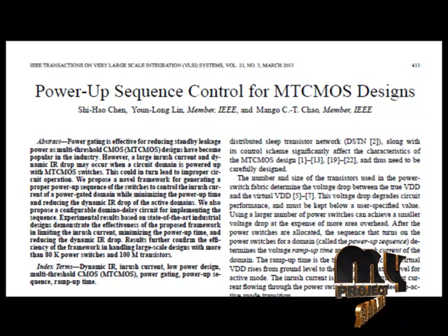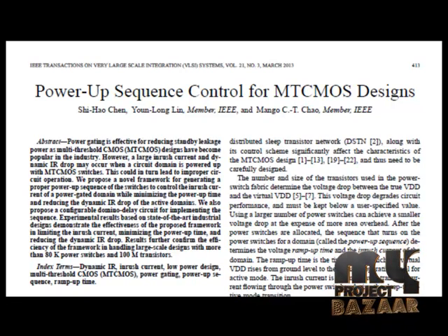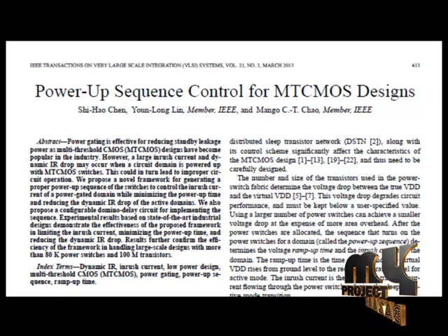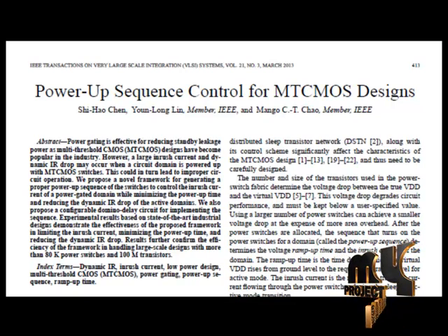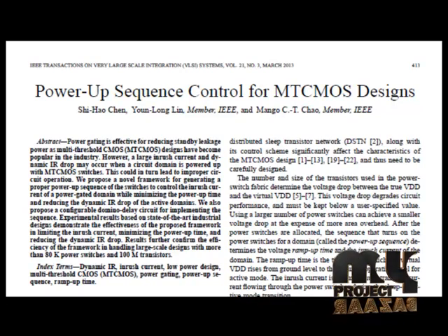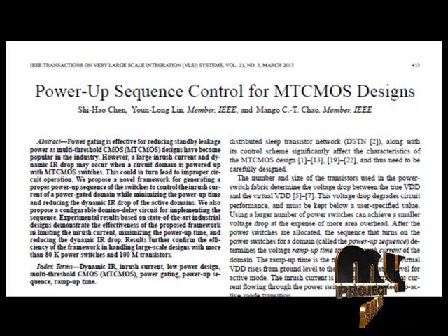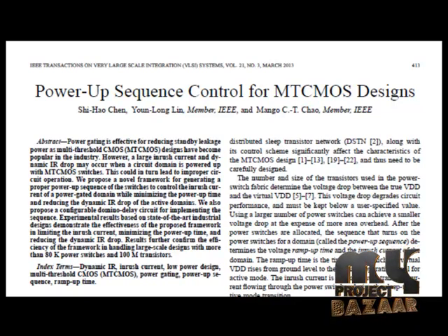Dynamic power losses are significant but can be mitigated by techniques such as clock gating, which reduces the power consumption of idle sections of synchronous circuits. Asynchronous designs offer these advantages inherently, as they are data-driven and only active while performing useful work. In other words, asynchronous circuits implement the equivalent of a fine-grained clock gating network.